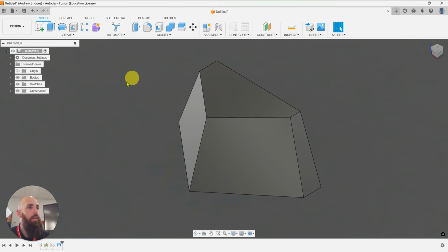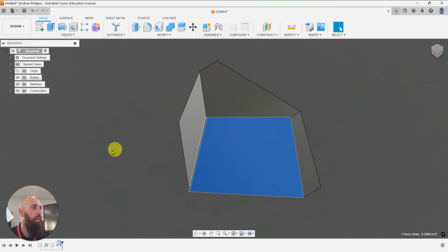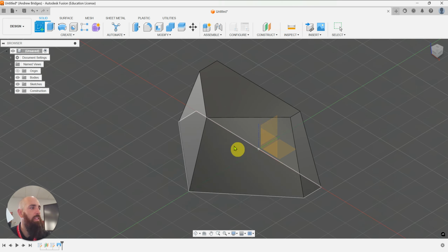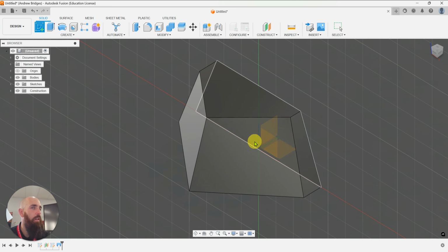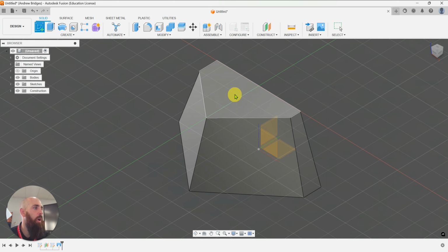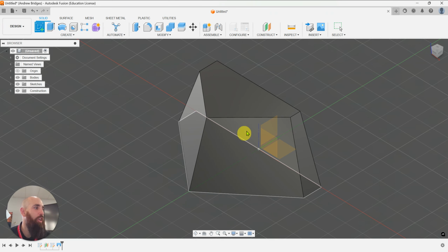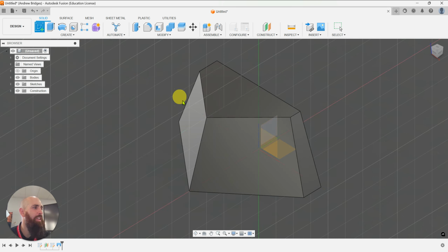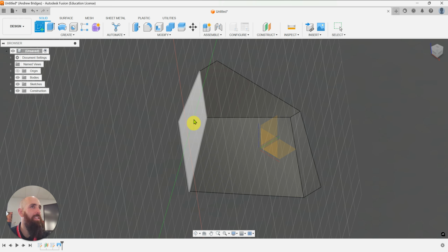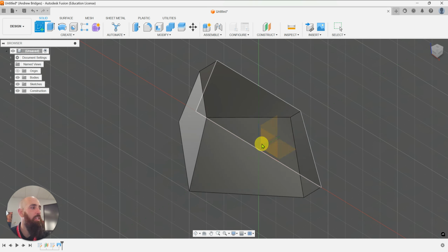Now the next thing, we're going to be sketching on the front faces of the part. However, it's not letting me choose that as a sketch face. The reason for that is, do you remember when I made that top sketch purposely wrong? If there are any problems with your two sketches, this face won't be perfectly flat, and therefore we can't sketch on it. That's why we can't sketch on that. This side should be okay, and it is. We can sketch on that because I got that side of the sketch correct. This side needs some help.